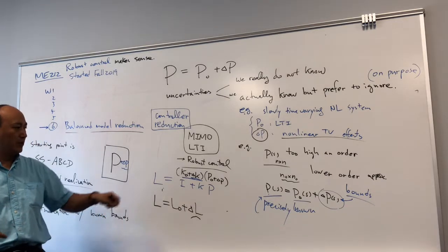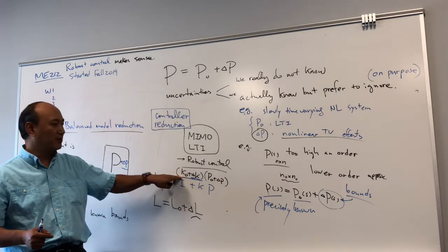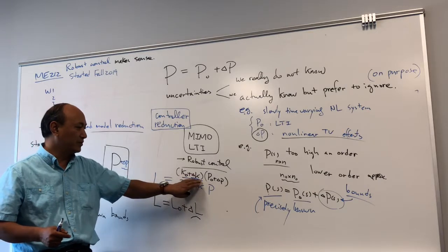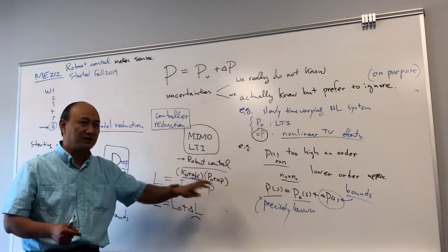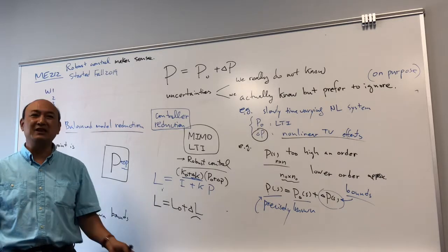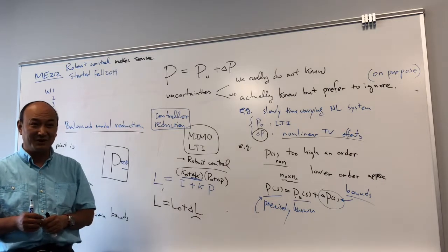So you probably want to do model reduction for the controller using an approximated realization, and if you know the error precisely, it can be converted to plant uncertainty. Then you redesign your system. Then done. See what I mean?